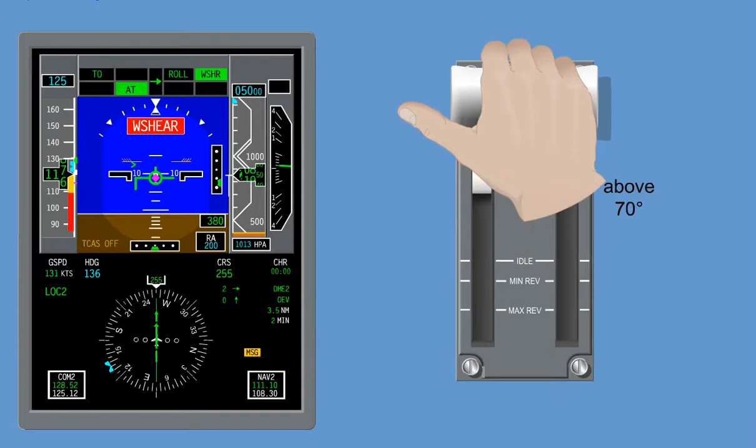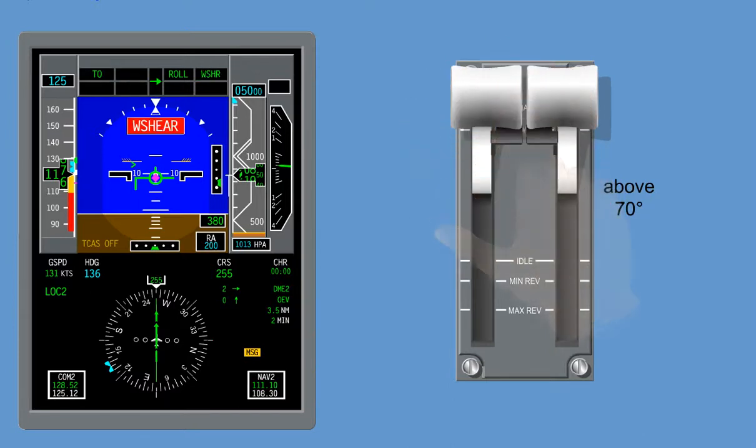In this condition, all the other flight director modes are cancelled, and the altitude pre-select, go-around, and take-off modes are inhibited while in a caution or warning wind shear condition. No lateral mode is inhibited while in wind shear mode.